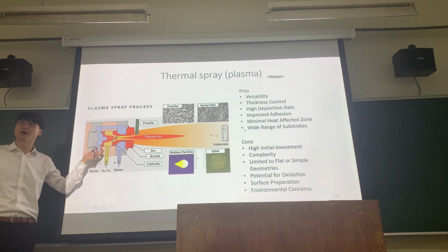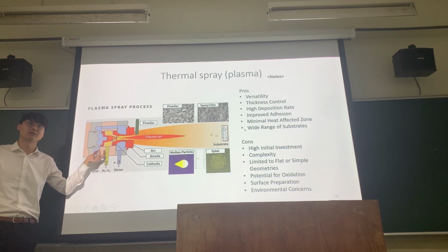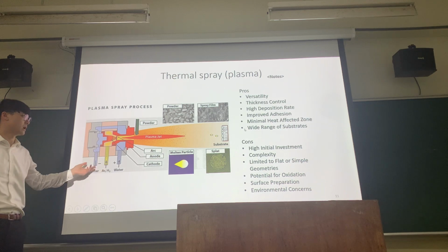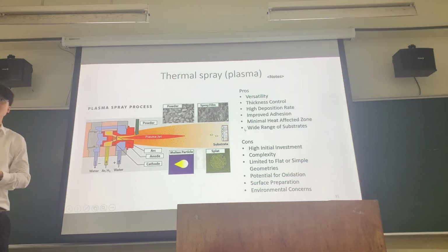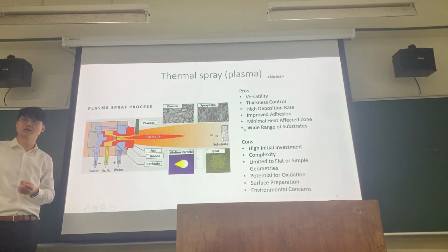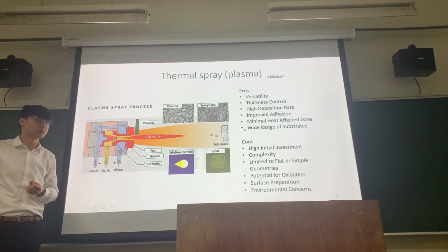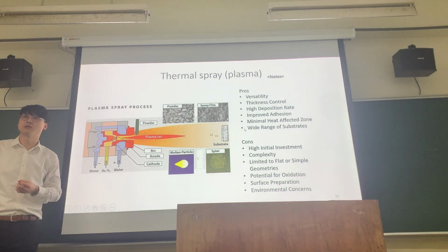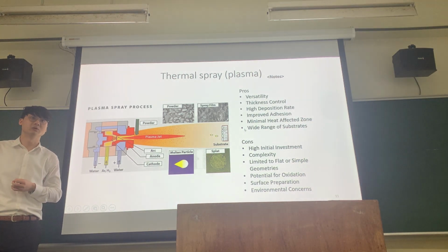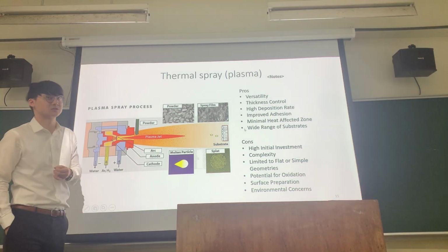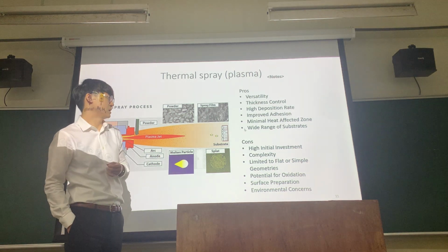Hydrogen is not cheap to get, and it is highly dangerous. It will explode. The cathode, anode and arc are also consumable products that are easily depleted. So the entire setup is quite expensive, not to mention the safety concerns and the regulations you have to go through. So a lab with a single spray system is really quite a big investment.